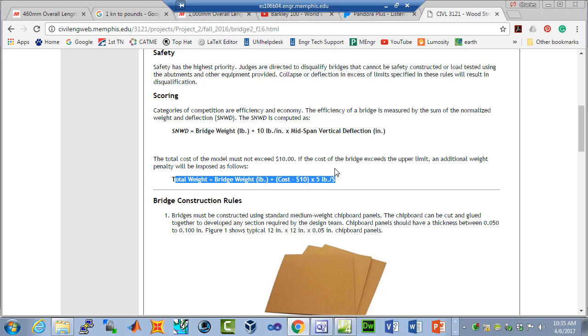See that? Another interesting thing that we're going to have to do is over the last 3 inches of this element, we're going to have a distributed force, right, of 40 pounds per inch. And then really over the first 3 inches of this element, we're going to have another distributed force of 40 pounds per inch. We haven't talked about that before. How do we have a load that's not over the whole element, just over a partial part of the element? So we're going to have to deal with that too. So I want to talk to you about this first before we dove into the SAP2000. This is the model I'm going to build, and then I'm going to apply these loads, and then we're going to calculate the displacement. And we're also going to enter in our property values. Okay? So any questions about that before we dive into SAP?